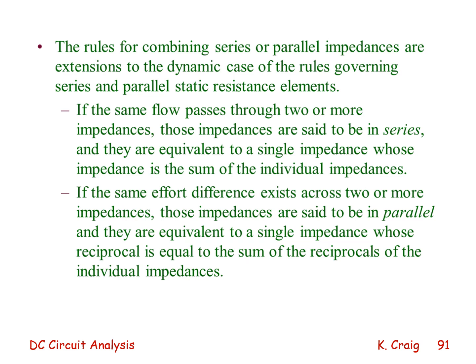The rules, as we know, for combining series or parallel impedances are simple extensions to the dynamic case of the rules governing series and parallel static resistance elements. If the same flow passes through two or more impedances, those impedances are said to be in series, and they are equivalent to a single impedance whose impedance is the sum of the individual impedances.